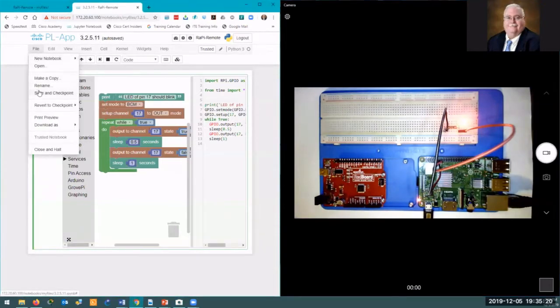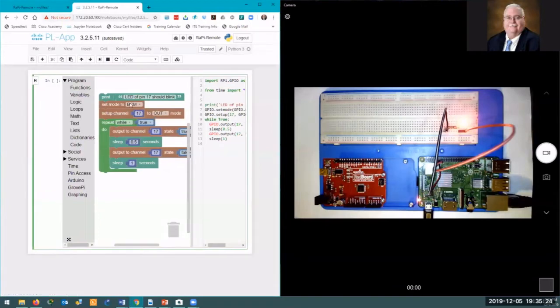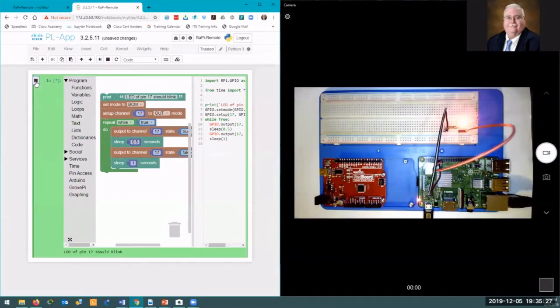Note, it's a good idea as with any program to save often. Follow the instructions and complete the Blockly program. When you click Run, the LED should begin blinking. Troubleshooting steps to keep in mind: program coded incorrectly, bad or backward LED, or wiring issues will keep the lab from working correctly. To extend this lab, challenge your students to write Morse code to blink SOS.